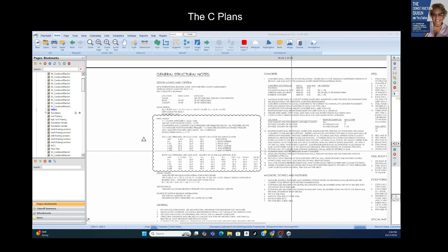The roof then sits on what? On the roof deck, the trusses. That's carried by the beams. And then we go down to the beams and the girders. The beams and the girders again collect the roof and the floor loads, and they distribute them to the columns or the load bearing walls, which are typically the walls of the perimeter of the building and some that come in the building. Then we have the columns and the bearing walls.